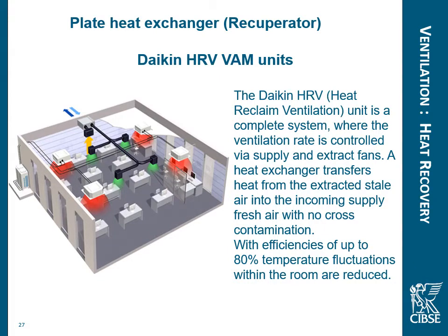So just to recap in that office there, the outdoor unit, this is the VRF unit outdoor, which is often used in modern offices for doing heating and cooling. See, it's providing the heating air there. Now remember, this air is just room air that's recirculated. In this system, the air in the room never changes.